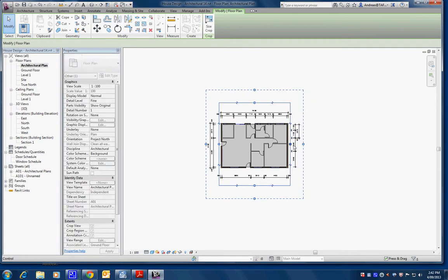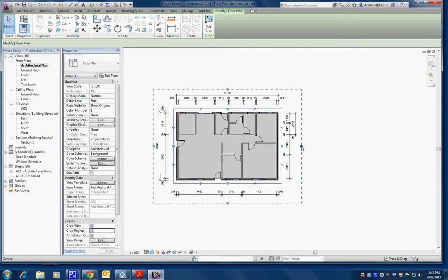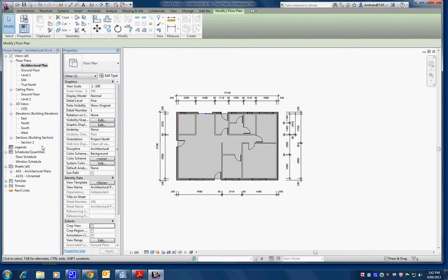All I've got to make sure is that my dimensions, for example, are within the dashed limits, and they should still show up. Yeah, that's right. You can see here, if I go over here, I'm missing some of the dimensions, so I need to be careful. I can adjust that separately, each side. That's good. Then I can just turn this off, otherwise that'll print, so I want to turn that off after I've adjusted it, and apply that.